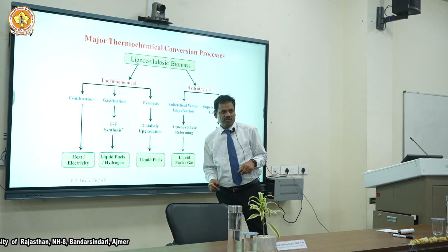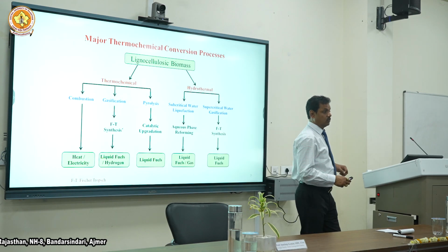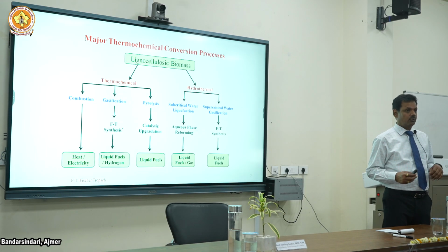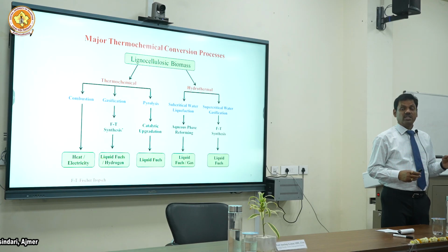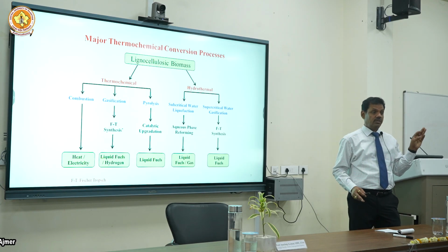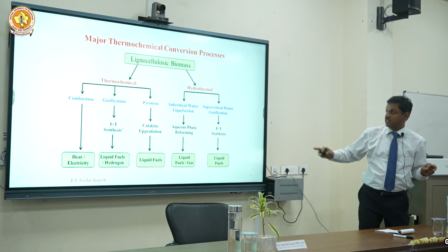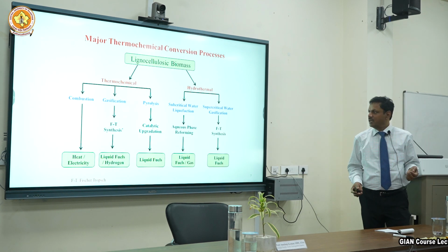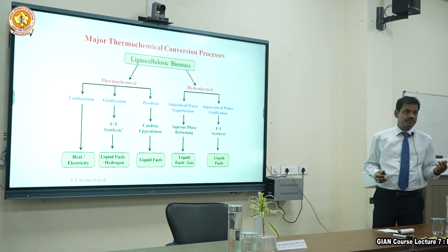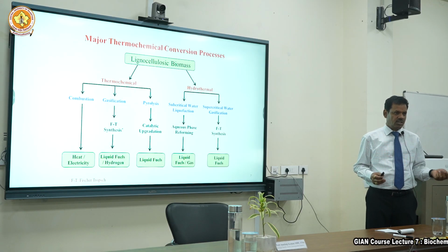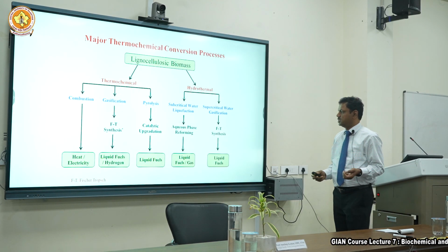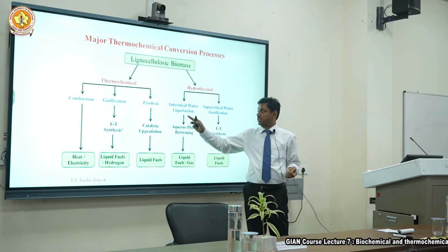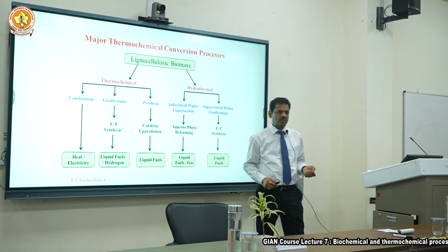Then pyrolysis. You don't want to go to that high temperature in gas phase. You really want to make liquid out of it. No matter which process you do, you will get solid, liquid and gas. With combustion you get mostly gas, some carbon dioxide. Gasification you will get all three: some tarry material, some char. Pyrolysis again you will get all three, but here you want to get more oil, or more char.